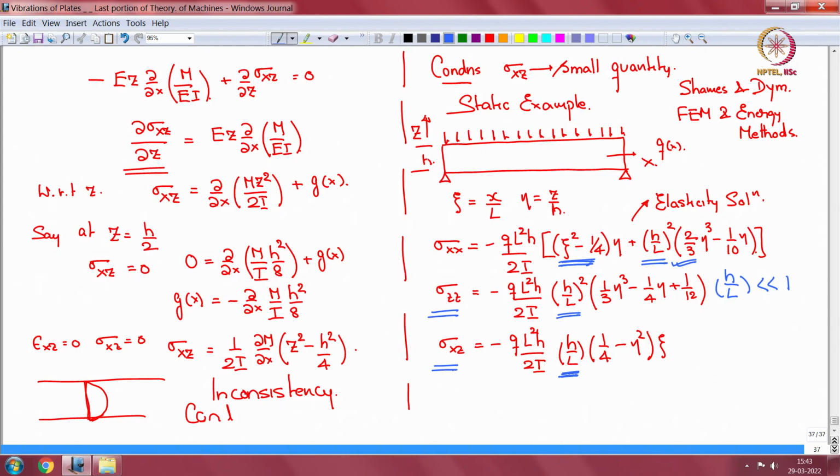That means the thickness should be much smaller than the other dimensions of the structure, which suits our thin plate study. So if our structures are thin enough, then the Euler Bernoulli level of approximation is good.